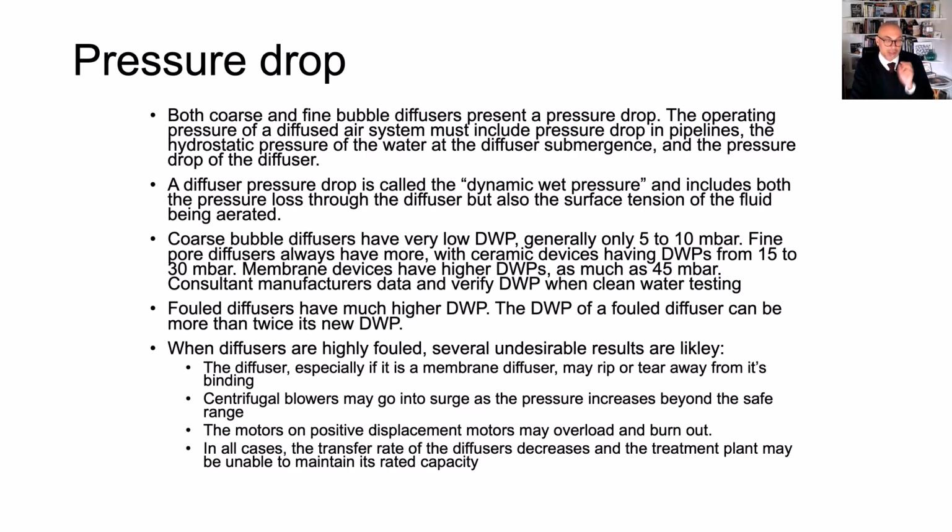Remember that coarse bubble diffusers have a very low pressure drop, so it's inconsequential. It doesn't change with time because they don't foul. But fine pore diffusers have a high pressure drop when you begin, and it gets higher with time. So at some point you might run out of pressure if your blowers have a limited pressure. It's very, very important to remember that. If you have low efficiency, you may have oxygen deficiency. But if you have low pressure in the blower, you don't have bubbles coming out at all.